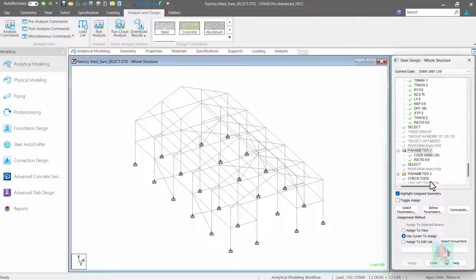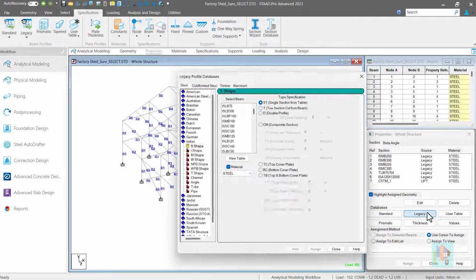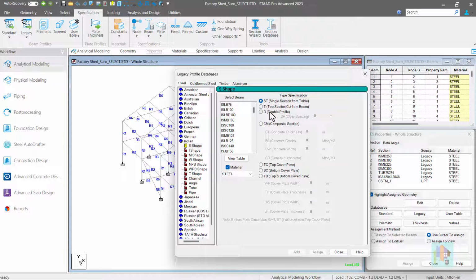Note that optimization is based on standard shapes. There are a few conditions when we don't use a higher section, but rather use a weaker section with customization like web stiffener or flange cover plate, even custom shapes like cruciform or double eye section. Those are not considered during optimization.